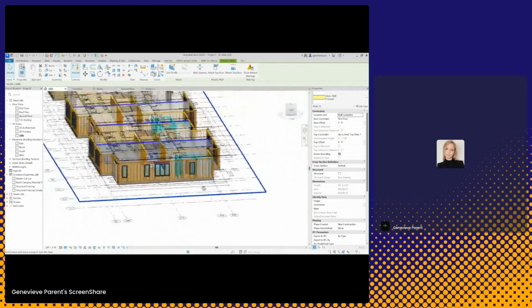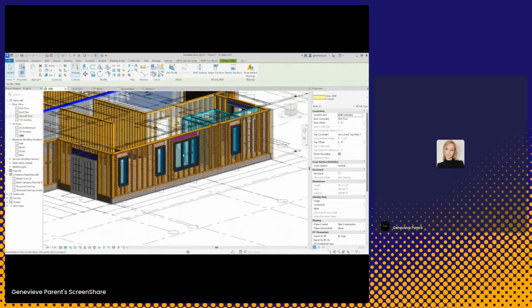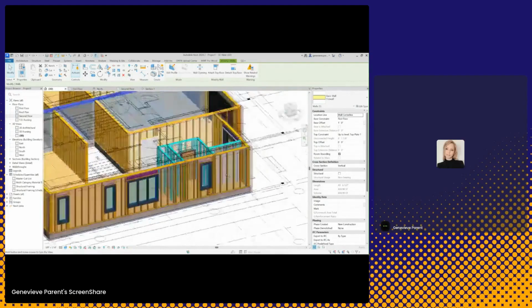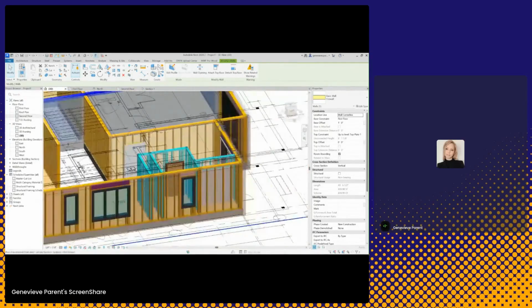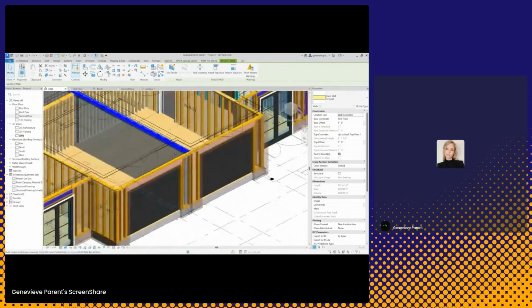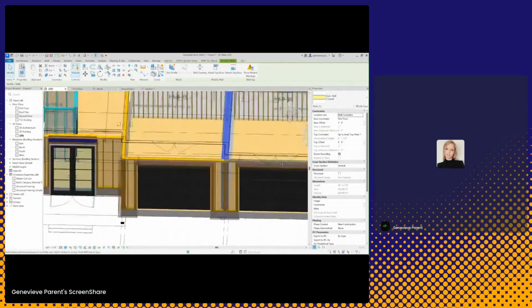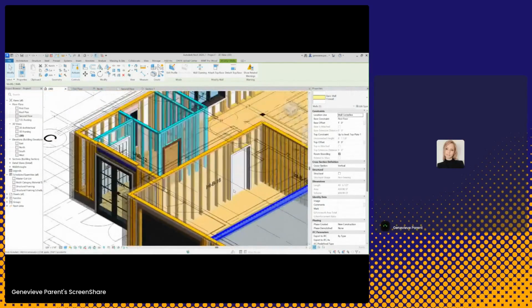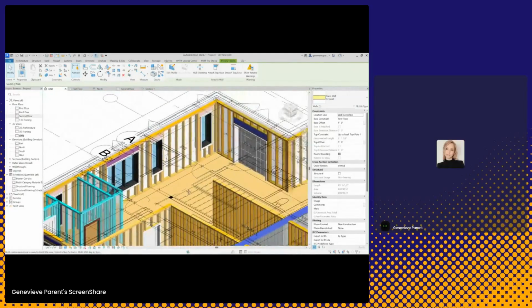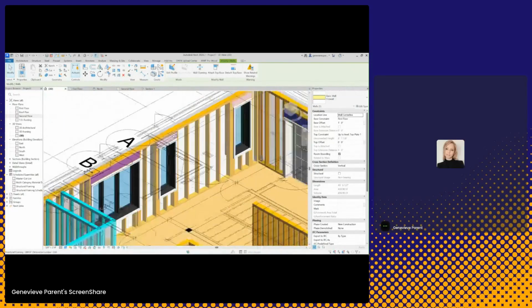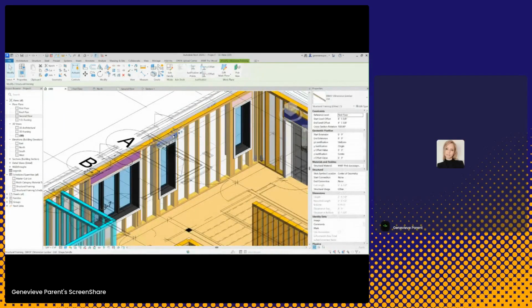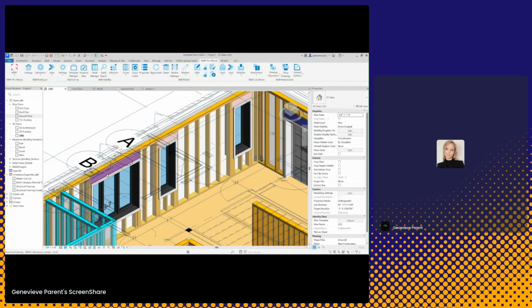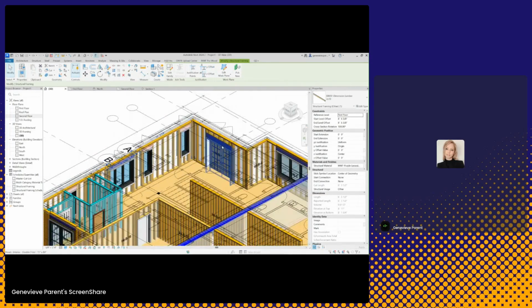And as you can see, when it comes to the openings, I had pre-configured some openings in advance for the interior walls as well as for the exterior walls. I'm just going to turn this around a little bit. So I already had headers that were specific sizes assigned, 2x8s. These ones are probably 2x10s. Exactly.